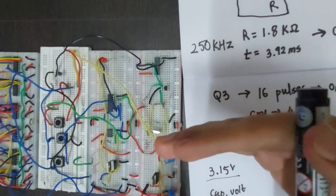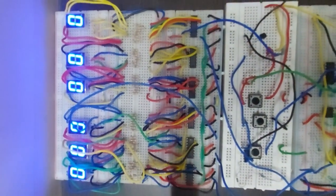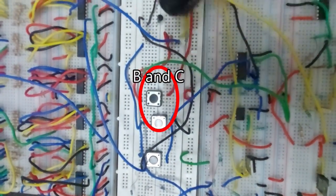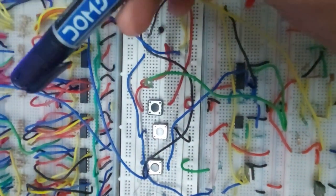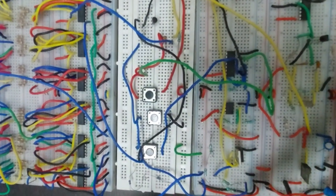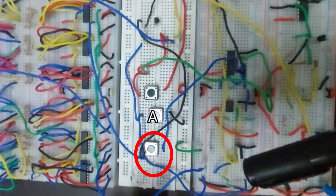At last we have the counter circuit, but before that we need to understand these three switches. Switch B and C reset the whole circuit, including all counter ICs, and discharge the capacitor, which we are going to plug here to measure the value of the capacitance, and switch A charges the capacitor.